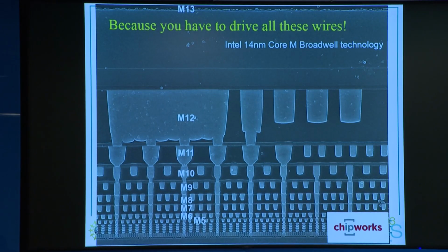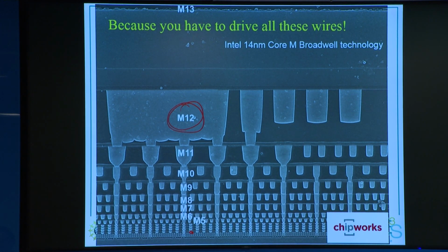So I have here a picture of a modern chip, and there are actually 14 levels of metal. And you can only see it up to number 12, and you go down, and way down here at the bottom are the transistors. You can barely see that at the bottom. And there's actually 2 more layers that don't even fit. And so you can see that the transistor has a very difficult job because it has to drive all the capacitance of all of that wiring.